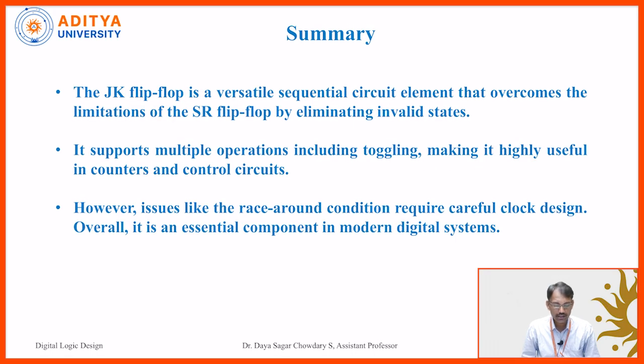Coming to the summary, the JK flip-flop is a versatile sequential circuit element that overcomes the limitations of the SR flip-flop by eliminating invalid states. It supports multiple operations including toggling, making it highly useful in counters and control circuits. However, issues like the race around condition require careful clock design. Overall, it is an essential component in modern digital systems.